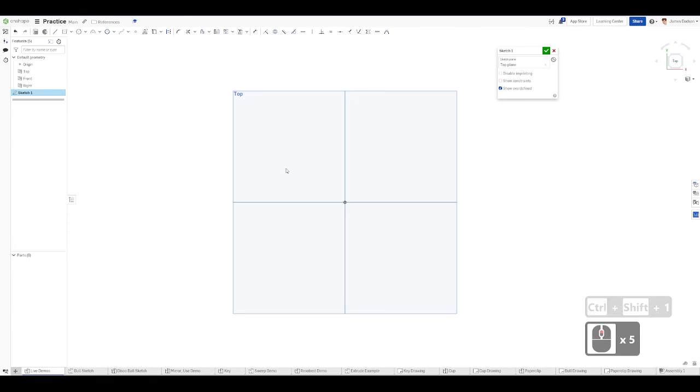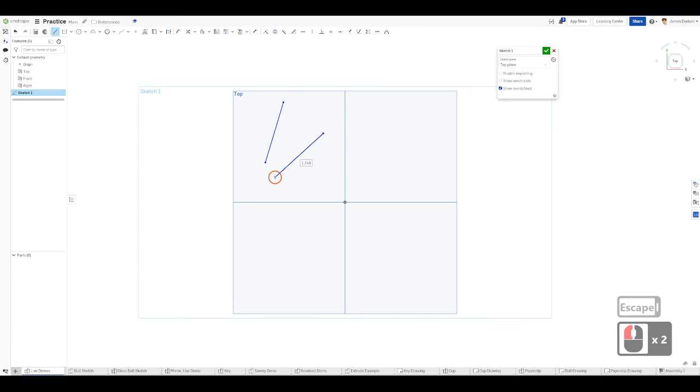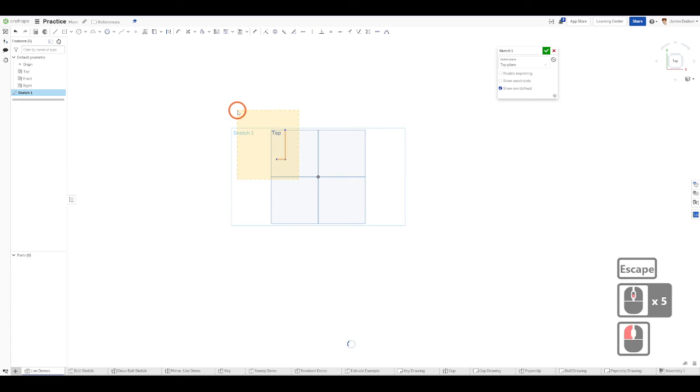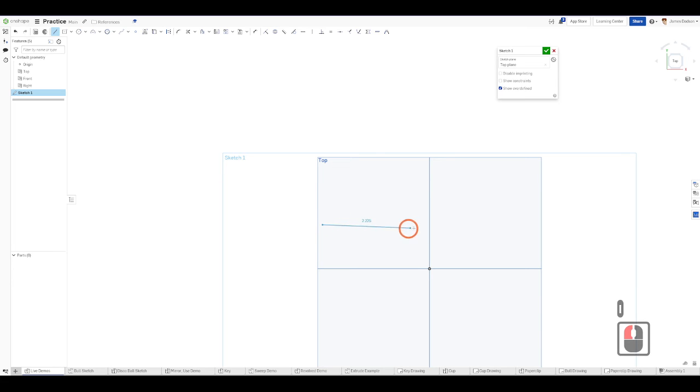So to show both of those off, for parallel, let's say I've got two lines. Press B or select this. This icon up here. Looks like two parallel lines. Don't get it confused with the equal icon up here. Now they're parallel. Perpendicular, same thing. Got a line, and I've got another line. I want them to be perpendicular. Press that. This will get auto-suggested too. If I've got a line and I'm creating another line, it'll auto-suggest that they're perpendicular. So that's helpful.